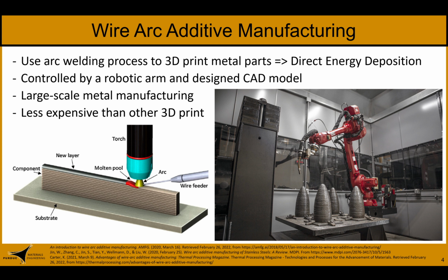As printing proceeds, the melted wire is extruded in the form of beads on the substrate. As the beads stick together, they create a layer of metal material. The process is then repeated layer by layer until the metal part is complete. Wire arc additive manufacturing is particularly suited to manufacturing large-scale metal parts, as the robotic arm of the machine has freedom of movement.